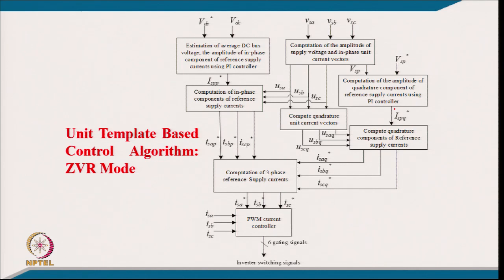and then what we have to do, we got already the amplitude, we have a phase voltage. So, by this transformation we have to compute the quadrature template, because these currents are the reactive current. So, we must have a template which is 90° leading than the voltage. From this template we will discuss how we get the relation, and multiplying this template with the amplitude we will get a quadrature component of supply current.